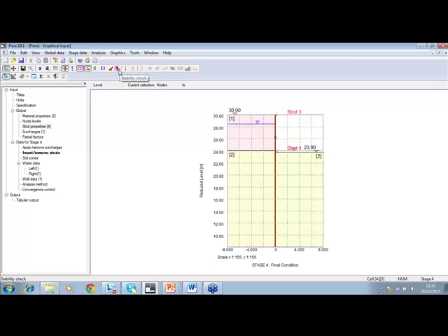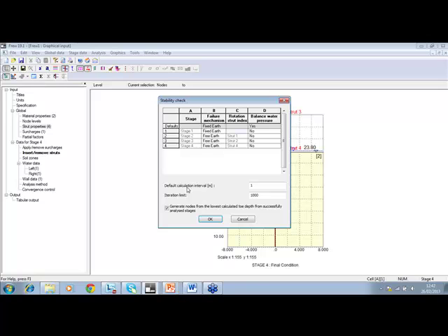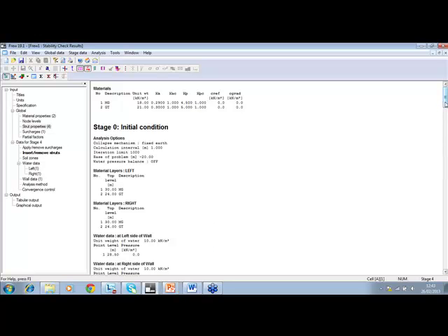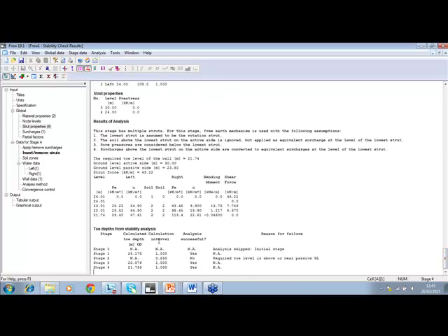So there's the stability check icon. I'm going to click off this so that I can have a look at all the toe levels which are generated. So as you can see, we have a number of toe levels here. The lowest toe depth is 20.57 meters. Okay, and now I'm going to click on this icon here with a number of dots in it to generate the nodes.